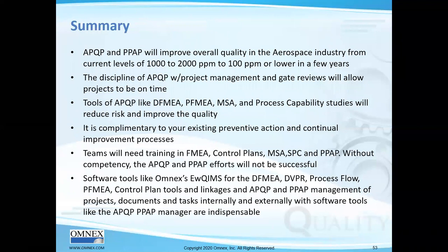Okay, so just a little bit of a summary. It can improve your overall quality. It can reduce your PPM levels from in the thousands, or your scrap percentage from being high, down to that industry standard of 2% or less in just a few years. It does have the gate reviews, tools within APQP, your design FMEA, your process FMEA, your MSA. It's all going to help reduce the risks and improve the quality of your parts.